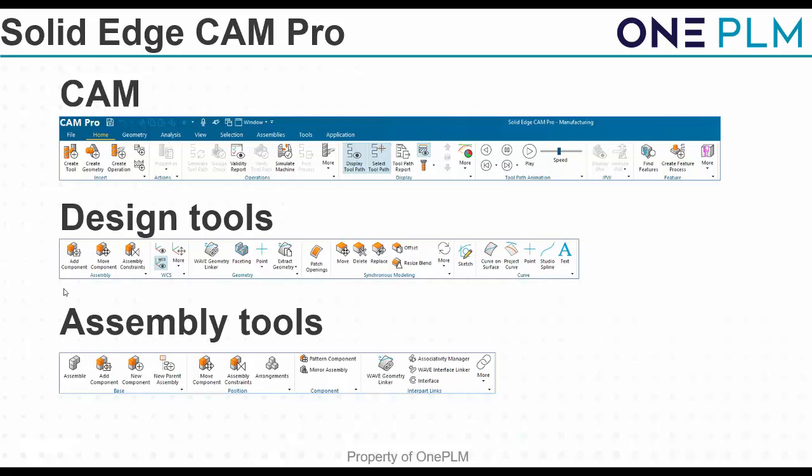Design tools. Quite simply, we've got the synchronous modelling, so you can push me, pull you, delete faces, delete holes, all the kind of manipulation that you might want to do. You can extract surfaces and edges, you can grow edges, pull edges, do all kinds of little tweaks that you might need to do just to help you with some of those complex parts. We can also patch holes as well, and there's loads of other clever stuff that we can do in those design tools, including the sketch tool here.